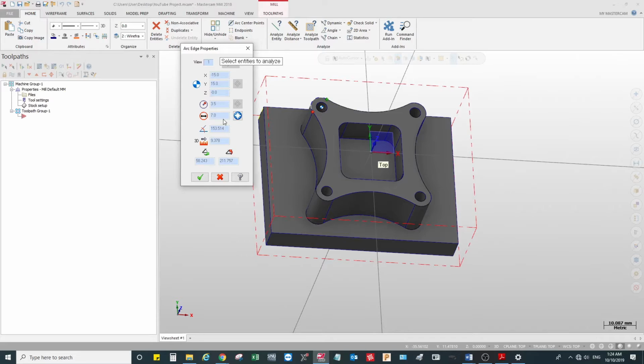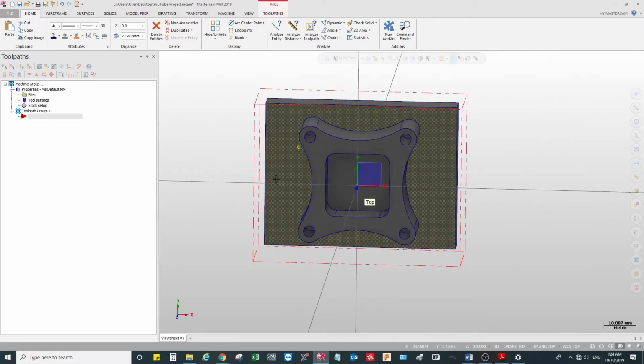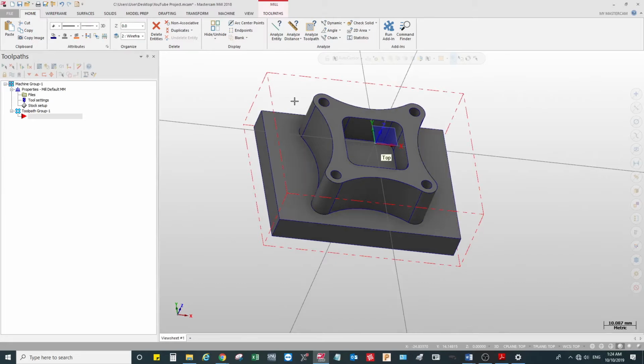It says 7 diameter. So if I have a 10mm tool, I can easily machine this profile. I can use the 10mm end mill to rough machine, leaving some stock on the sides, and later go ahead and give a finish pass where I can get the desired result.